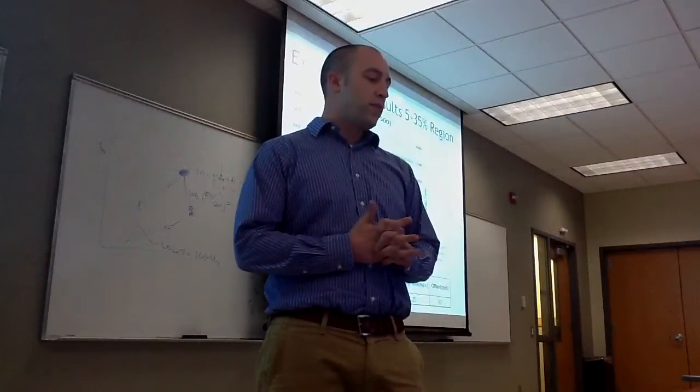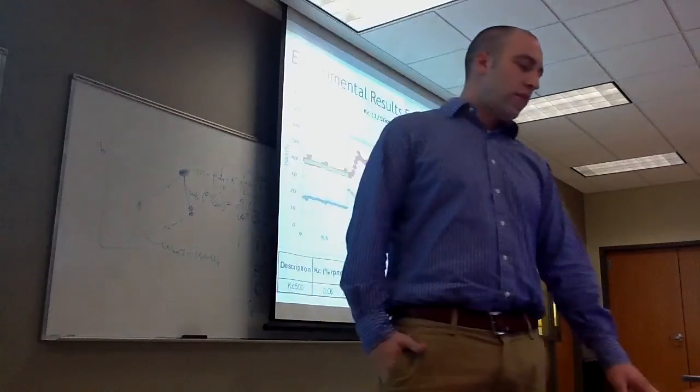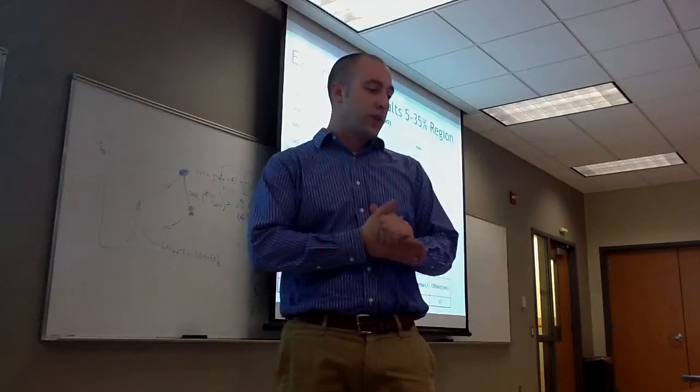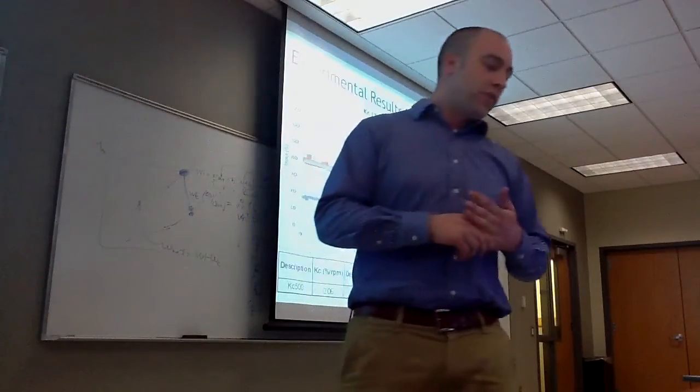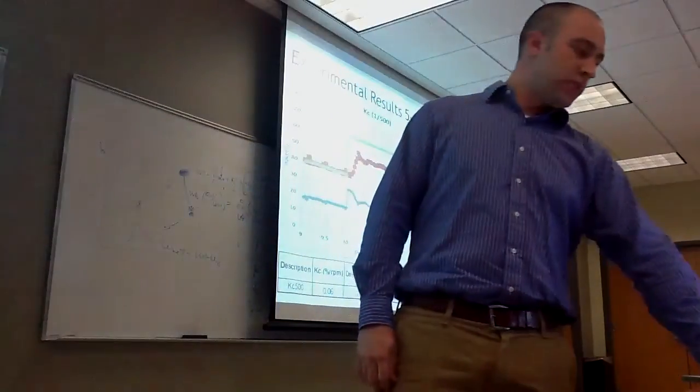Here's the graph for the 1/500th decay. Found the value to be 0.06 with a decay ratio of 0.9 and a settling time of 0.25 seconds, and it has an offset of 97 RPMs.